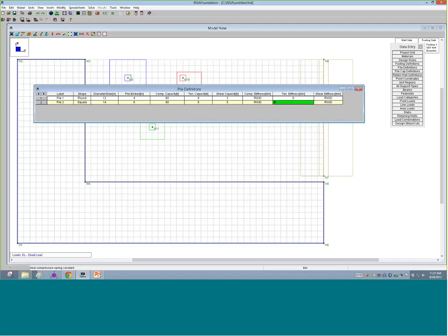So we're saying that it has no stiffness in the tensile direction. But in the shear direction, we're saying it also is fully rigid. If you want to tell the program, instead of rigid, you can say it has some kind of a spring constant capacity for stiffness. So if we say 100 kips per inch, that would be your compressive stiffness in that direction, and that would act more like a spring than a fully rigid boundary condition.